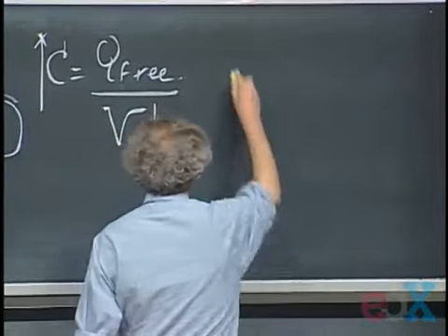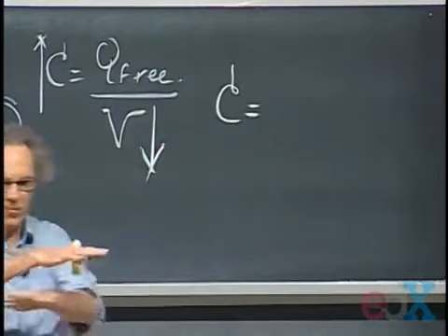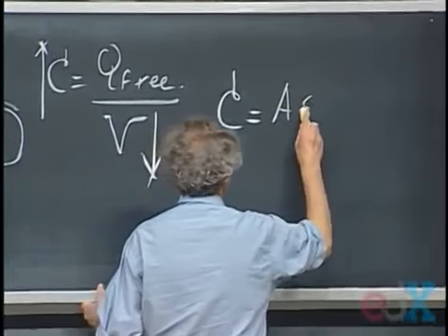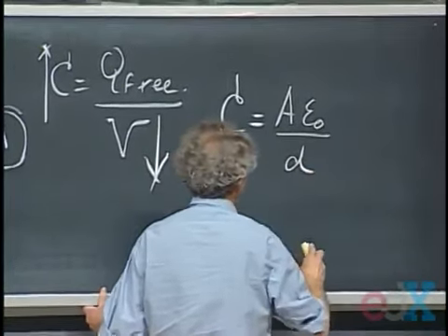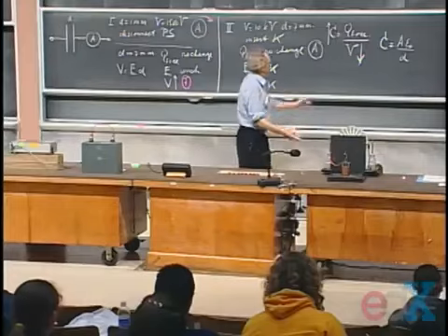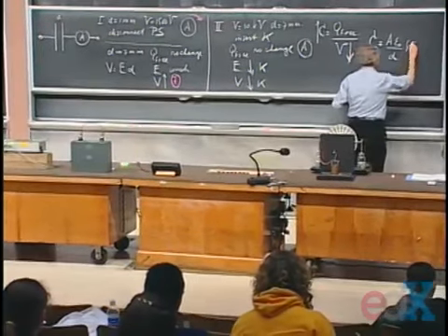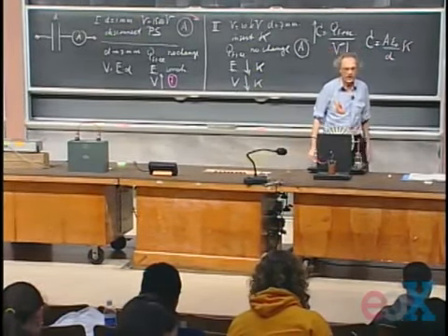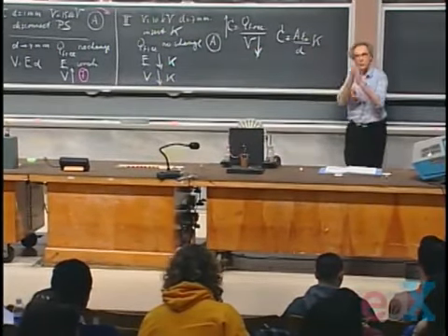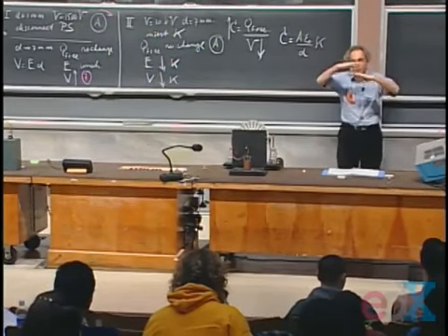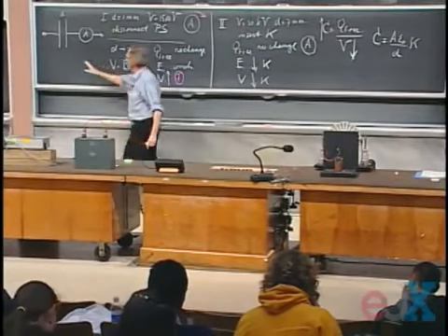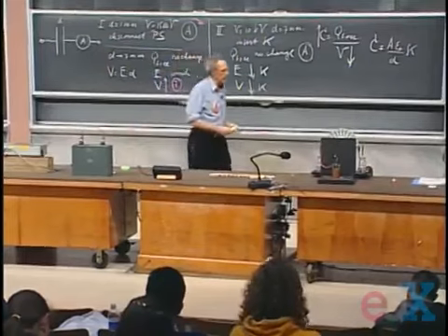And so, since the capacitance, as we derived last time for plane plate capacitors, I still remember it, was the area times epsilon 0 divided by the separation D, since we now know that with the glass in place the capacitance is higher by a factor of kappa, this is now the amendment we have to make to calculate capacitance. We simply have to multiply now by the dielectric constant of the thin layer that separates the two conductors. This is the layer that has thickness D that is in between the two plates. In our case, I brought in glass.